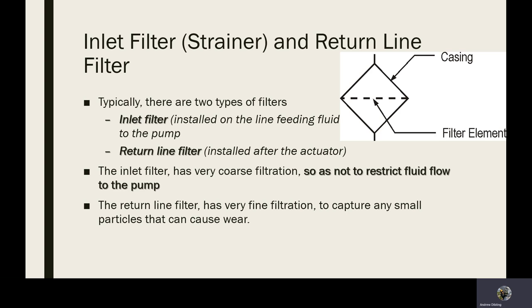It's generally a mesh, fairly fine, but not too fine, because you don't want to have a problem with suction across that inlet filter, because you can have low flow to your pump, which can cause cavitation, which is a deadly hydraulic fault. Actually, cavitation is one of the worst things you can do to your system.